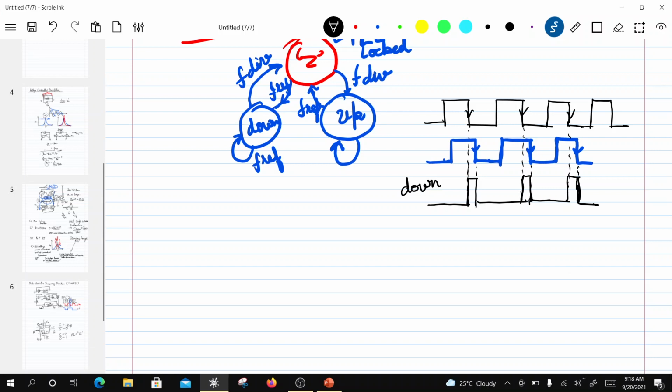Now what's happening in this case is, I can design this using a simple XOR gate. Whenever they are not equal, I am going to have a pulse, right? So this is when they are not equal, that's an XOR state, right? But then XOR is also going to come over here, which I don't want. I want to take decision only on the falling edges. So I'm not going to use XOR.